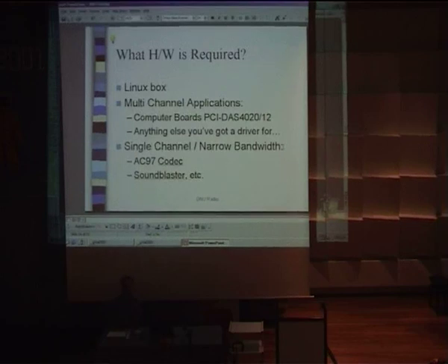The place that we've been looking mostly is really trying to drive the A/D converter as close as we can to the antenna, and we're willing to pay some money to get it there right now. So we're using a commercial off-the-shelf A/D converter board that will get 12-bit samples at 20 million samples per second. Now that's not the ideal, but it's something to provide today. That'll allow us to deal with an input signal that's at least 6 or 8 megahertz wide.